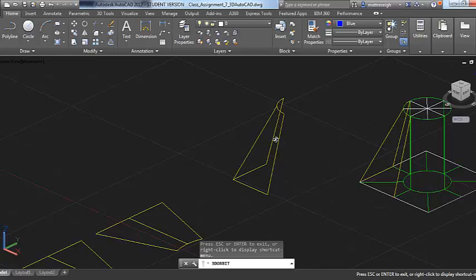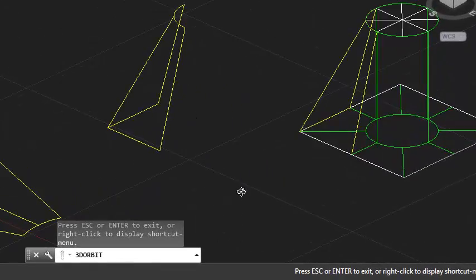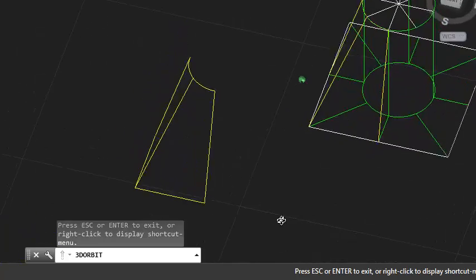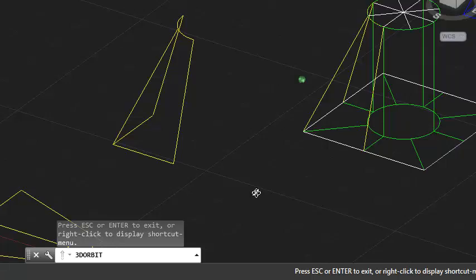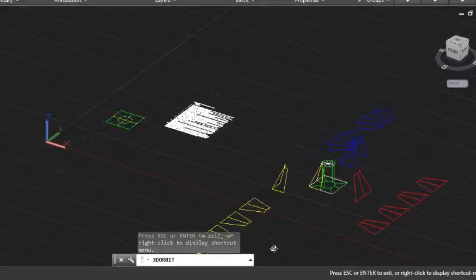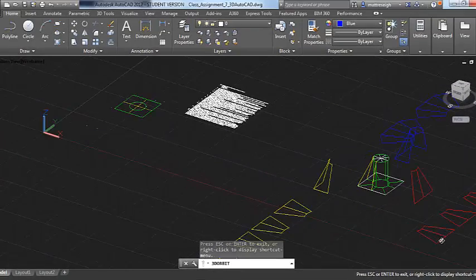If I did it like this, I would have 4 weld seams right down the middle of my squared area. So I'd have a weld seam in the middle of the 8-inch square to square to square, going from the middle of that up to the round area. So it's probably the least common way that I would make something. The interesting thing about looking at that is that the actual part is the same part. I just press broke it different to do this.